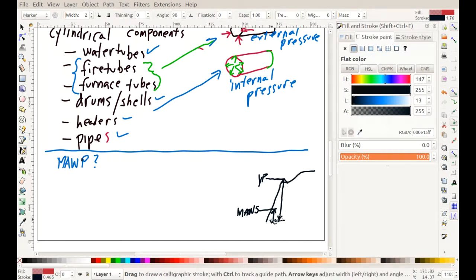So if we take the yield strength and divide that by the maximum allowable working stress, we get a factor of safety. And that's what you're talking about, right? We want to operate the boiler with material stress that is well below the yield point by some safety factor. Because even if we get a little overpressurization occurrence, hopefully our boiler isn't going to bulge or fail.